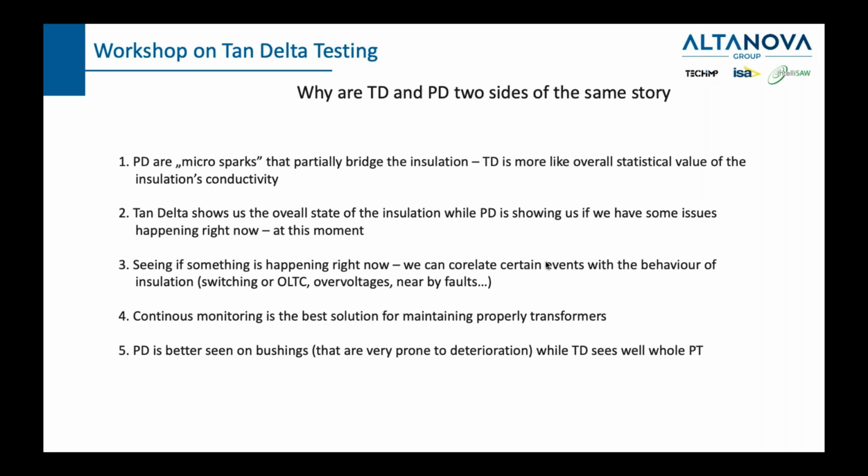Also, the best solution for properly maintaining not just the transformers, but all assets is continuous monitoring. We had a lot of webinars on the topic of continuous monitoring. We will have them again. And we are now also implementing the continuous monitoring. We already did that on medium voltage cubicles, because on a medium voltage cubicle, you can monitor not tan delta, but for example, temperature and partial discharge. So soon we will have some webinars on that topic.